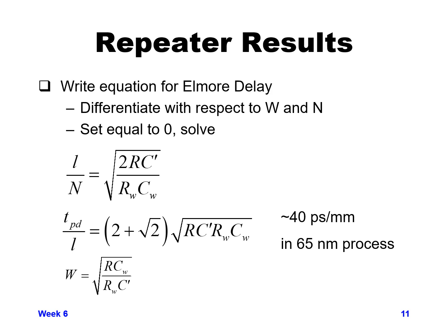But generally, I've never gone through the equations to try and find the ideal number of repeaters for a given distance. Generally, what we wind up doing at Intel, for a new process technology, is run simulations and vary the amount of distance. You'll generally have a certain repeater size that you find out is ideal, depending on what metal layers you're trying to drive your repeater across.